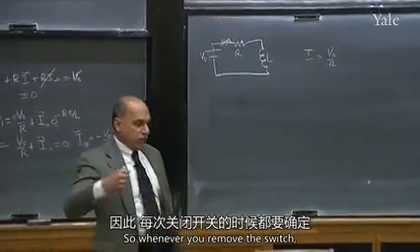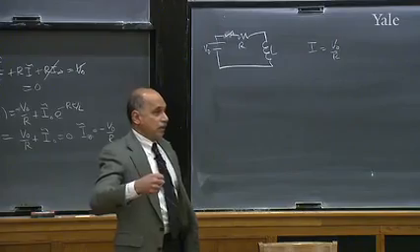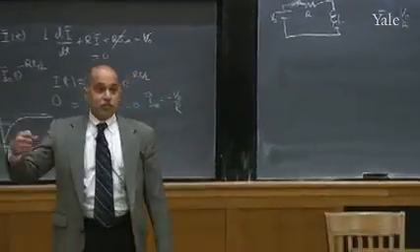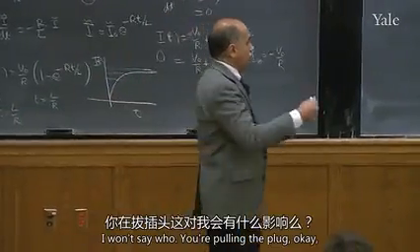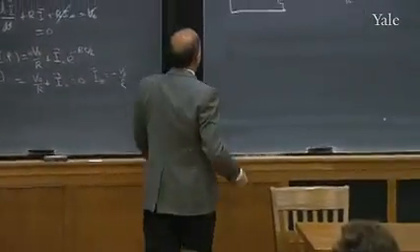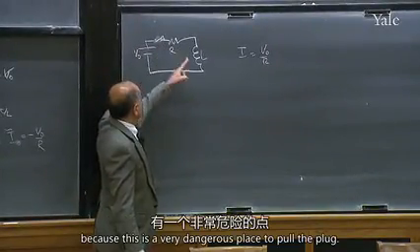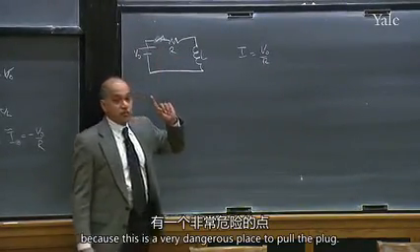So whenever you remove the switch, you have to be careful that there is no stored energy somewhere. You might think, hey, I'm pulling the plug. You're pulling the plug, okay? And what can it do to me? Well, it can zap you, because this is a very dangerous place to pull the plug.